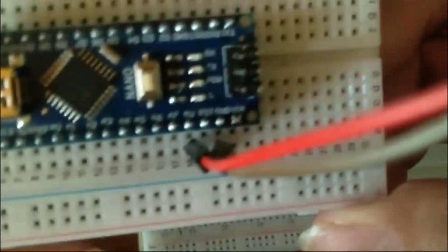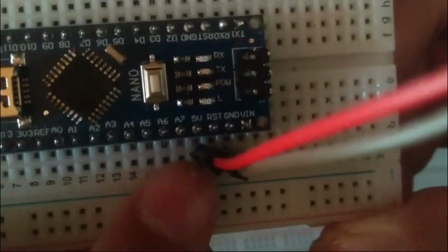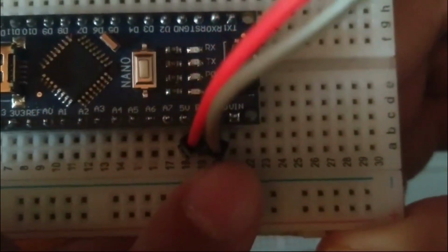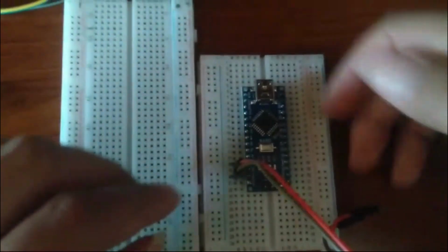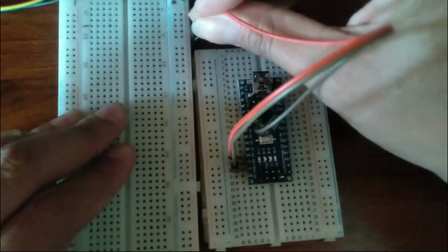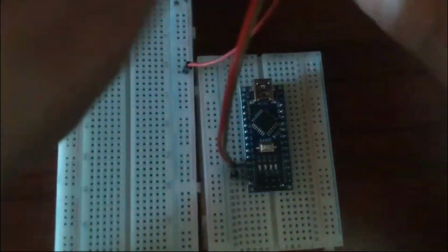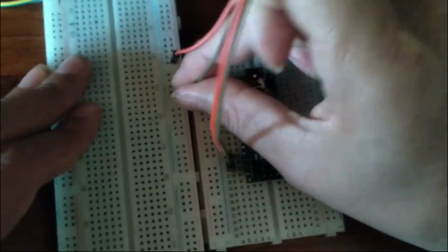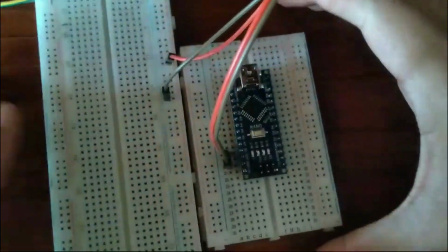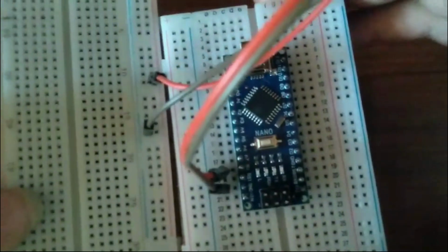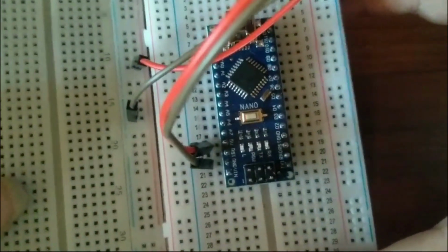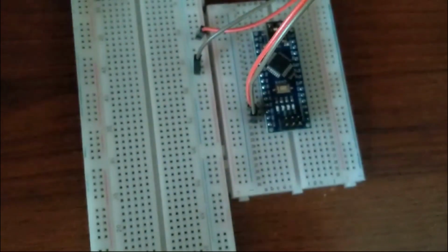So first of all, remember that we have to set up our power circuit. For that reason, you have to locate the 5 volts pin and the ground pin. The 5 volts pin you will connect to the positive bus, that is the bus that is red. Okay, you can put it in any place. Remember that it is a bus that will give off energy, and the same with the negative. But the negative, the ground, you will put in the black or in the blue. Okay, so with that we have already done this.